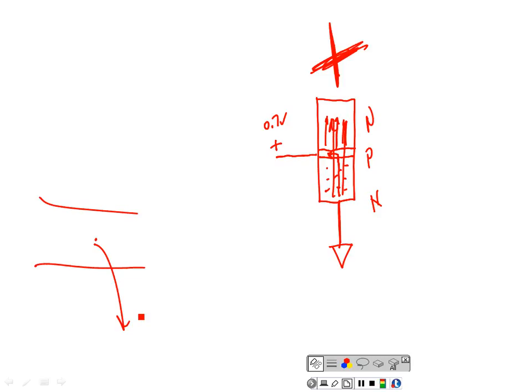So that collector up there is going to be a real high potential opposite of the emitter, and it's trying to suck these electrons, anything it can get, right? You understand? So a very little bit of current goes where? Out the base. So here we go. And there's our valve. I just turned my valve on. And just a little bit goes where? That direction right there. Okay, so that turns the valve on.